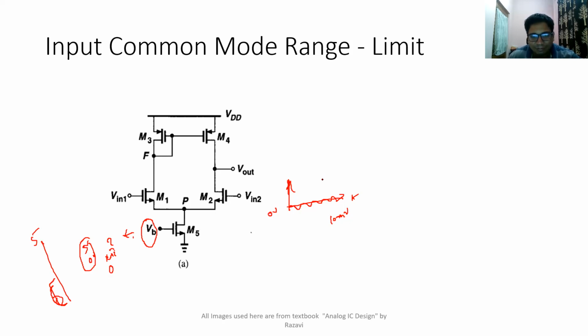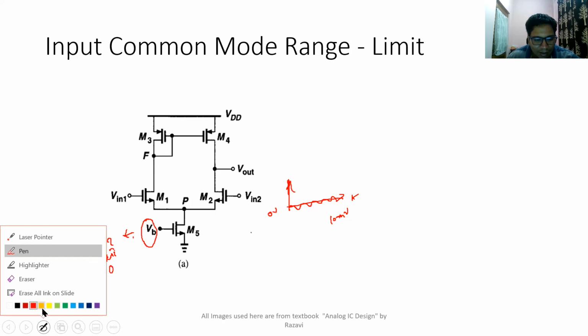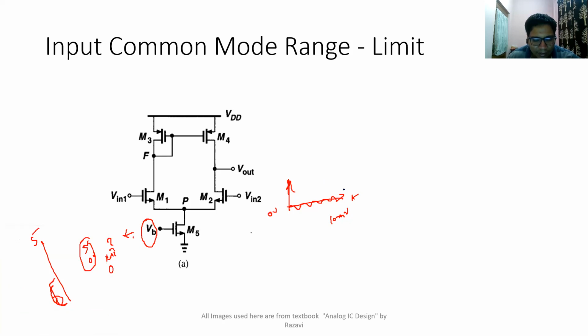No. Why no? It should be average in the active region. The waveform should be above the x-axis. You need to attach some offset. This is a pure AC signal. If you apply a pure AC signal here, it will not be able to cross the threshold voltage.